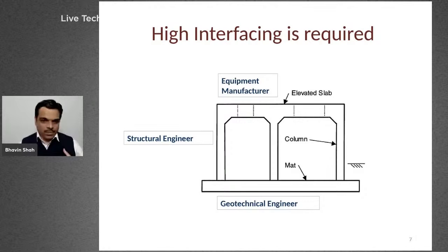So this is one thing I observed while working on a different machine foundation, that the type of load data, or let's say the extent of load data, varies from manufacturer to manufacturer. So that is the first activity which we need to carry out, which is to study the drawing of the equipment manufacturer. And I usually spend at least 2 to 3 days listing down all queries and doubts we have with respect to that equipment load data.